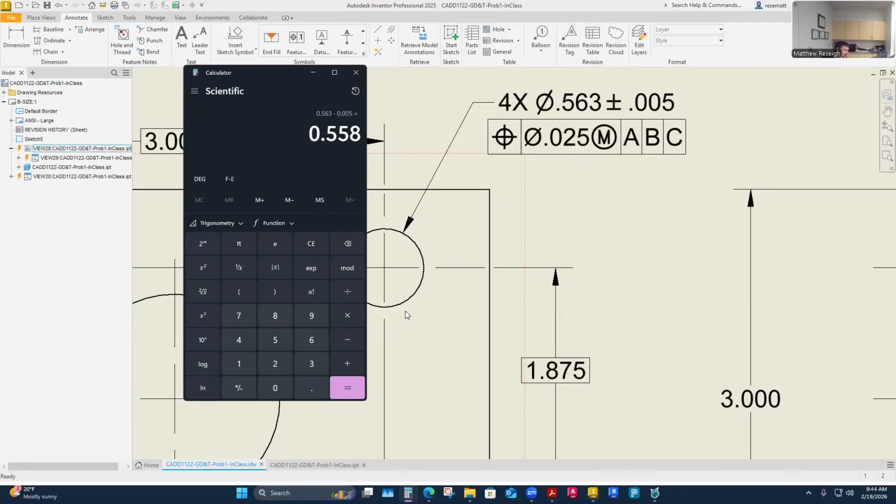So that's essentially what I have when I go back to my sketch and I have that hole size, or the little circle that's 0.025 in diameter. That's all the tolerance I have on a feature of size that is at its maximum material condition according to this GD&T symbol. Now as I depart, that's when I'll start to gain more than just 0.025 in positional tolerance, because as I depart from maximum material condition, I can add my departure to my tolerance.